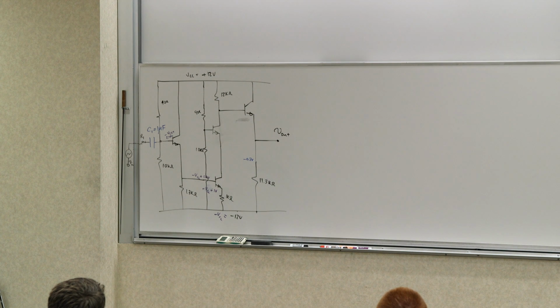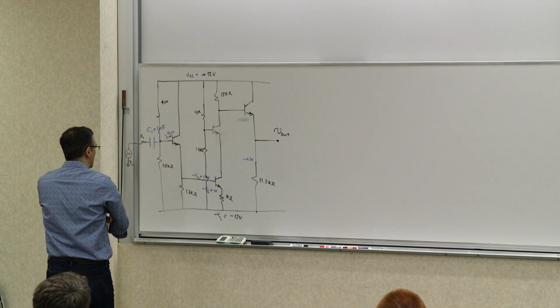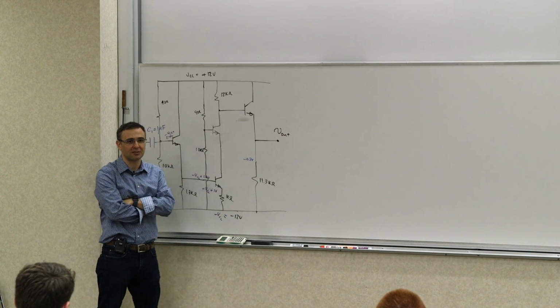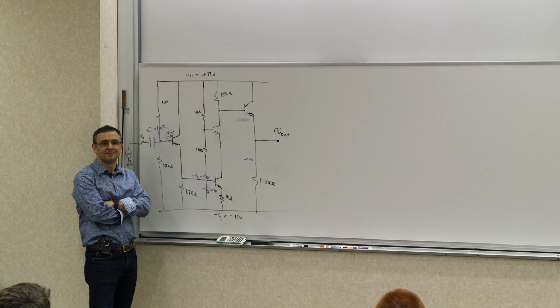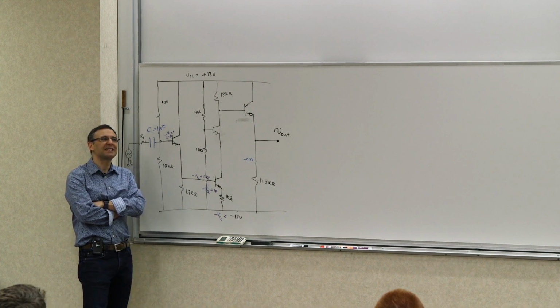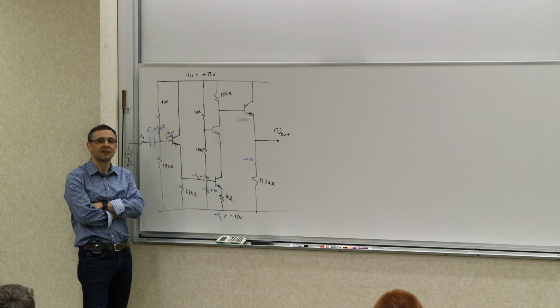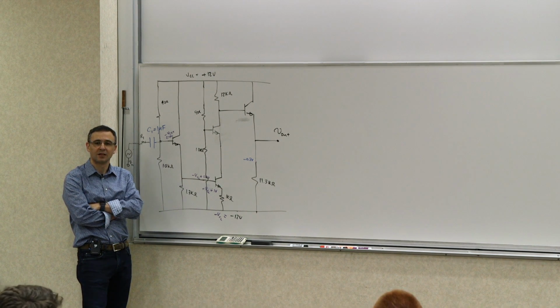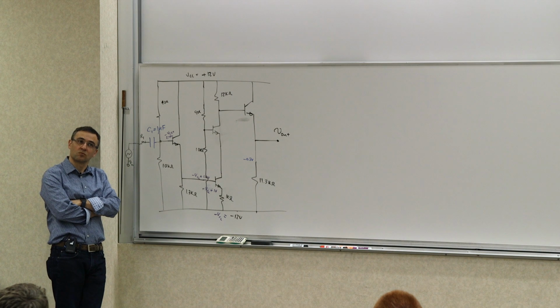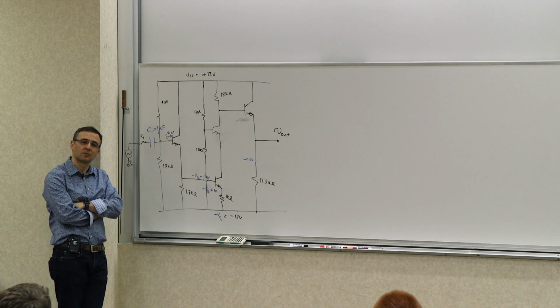So what do we do to save that, to help that? Can you think of a solution? You're in discrete design. You can add capacitors, resistors, etc. Can you fix this? Where do we care about this gain being high? Can we replace the resistor with something, like a reactive element, that won't kill the gain? Exactly. You need to use a reactive element.